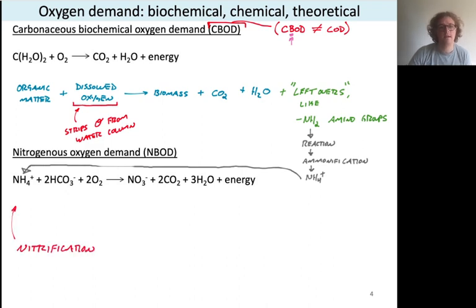So just like we see for carbonaceous BOD, there will be a microbially mediated process that is going to use dissolved oxygen out of the water column as part of this transformation. And so you can see I'm highlighting there in red those two O2 molecules. So as our ammonium is nitrified, we'll also use oxygen out of that water column.